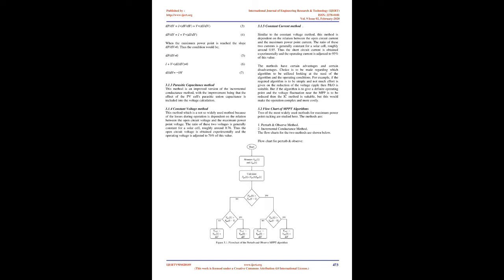2.3.1 The standard VI characteristic curve of a photovoltaic module. A photovoltaic module will produce its maximum current when there is essentially no resistance in the circuit. This would be a short circuit between its positive and negative terminals. This maximum current is called the short circuit current, abbreviated ISC. When the module is shorted, the voltage in the circuit is zero.